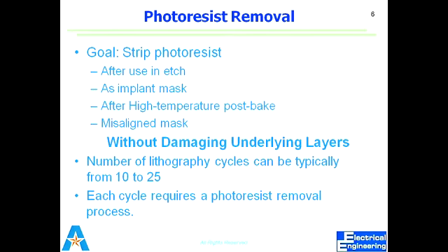This same thing can be done by photolithography as well. That is, if I have silicon wafer, so in photolithography, first of all you need to have the thin layer that needs to be patterned. In this case, you have thin layer, then the photoresist, because you need to do etching in this case. Now I need to pattern it.